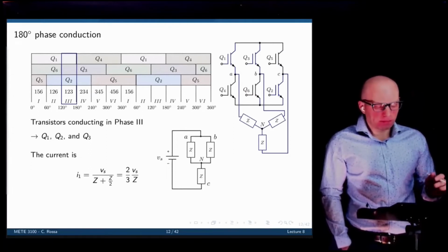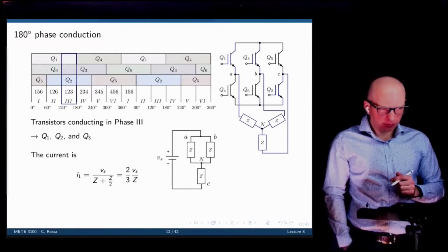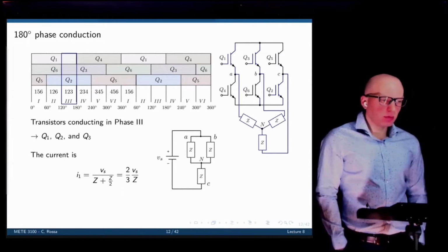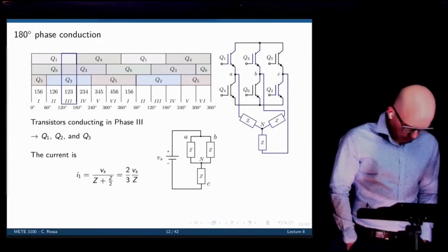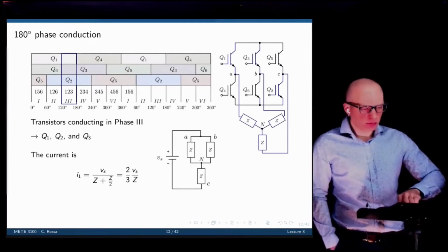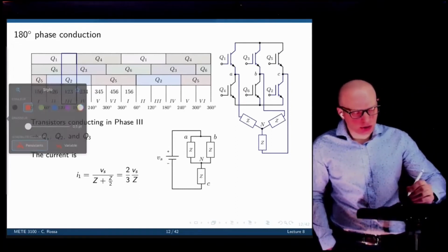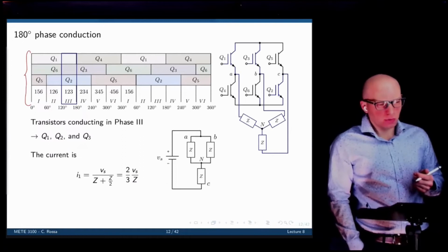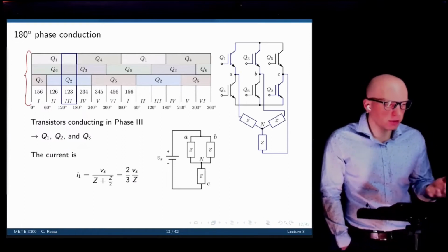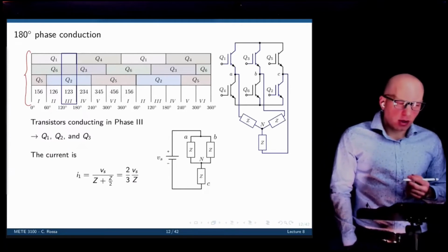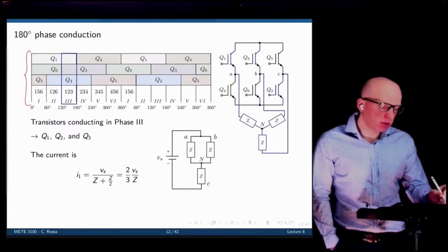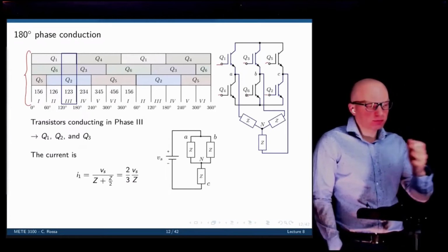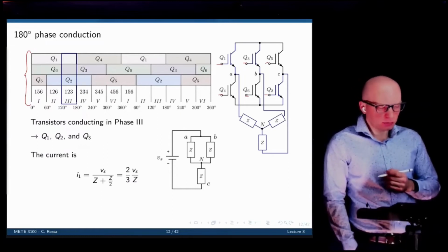I do have a quick question. Yes, go ahead. The switching of the transistors, we are still controlling it using like the optocoupler or whatever from the full bridge rectifier. Like we would have an external switching mechanism that controls the switching of those transistors. Yes, precisely. This logic that we are implementing here can run in a microcontroller, for example. Or in early days, this could be implemented with an analog system. And then you create 3 low power gating sequence signals, and they will go to each transistor there, depending on which phase of this conduction we are. Right. Okay. Thank you.